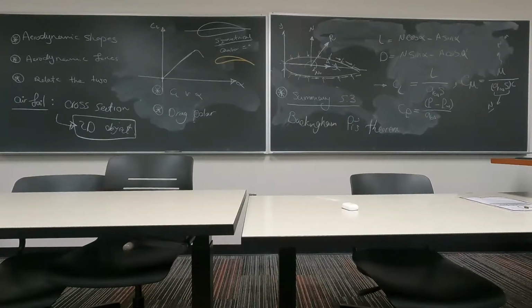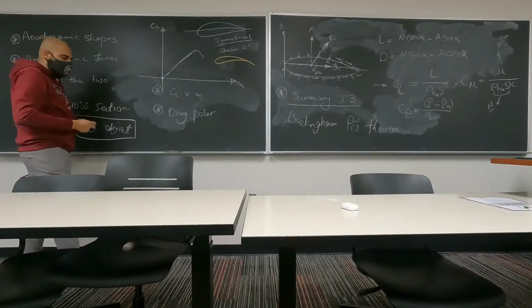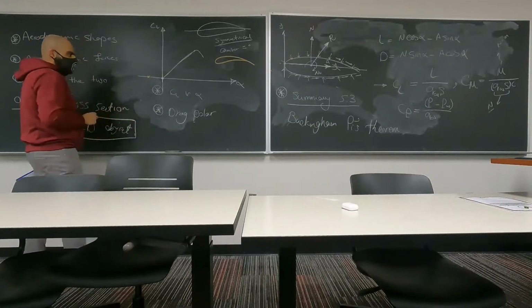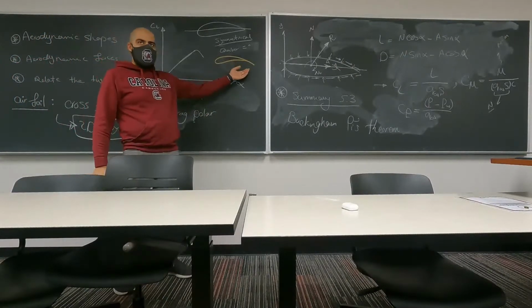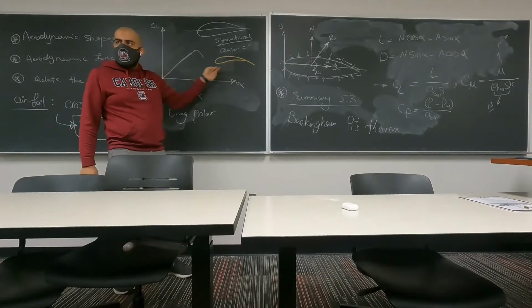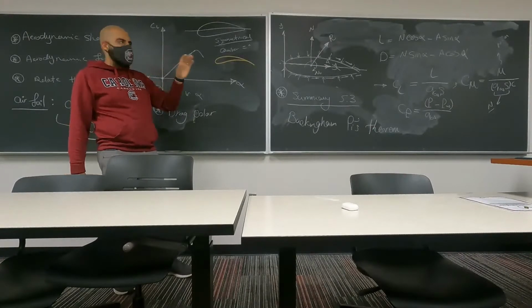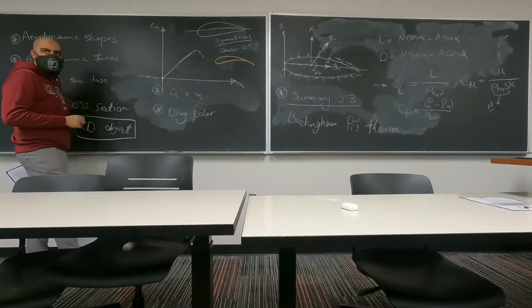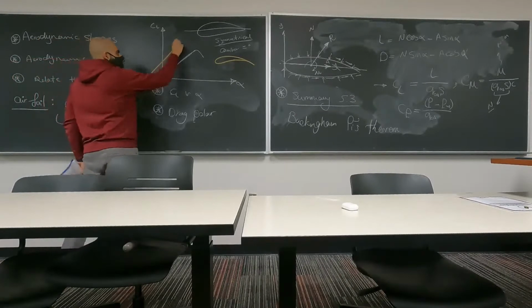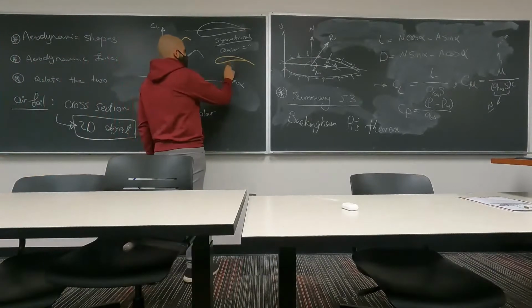It will start higher, or it will move to the left, right? So essentially, what Lawson is telling us is that because of the fact that there is some camber here, the streamlines flowing on the bottom of the airfoil are going to be always applying more pressure than the top, right? So we can actually get the 0 lift at a negative angle of attack. And this is what you're going to see with a cambered airfoil. But this is true for a positive camber, though.